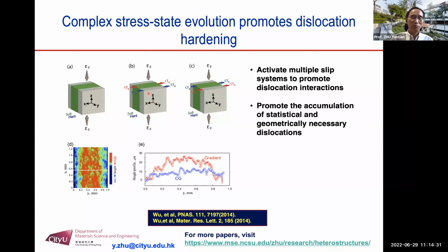And that causes a bigger problem because initially you apply a uniaxial stress. Now you have a two-dimensional stress as a result, because the center cannot shrink freely. It's constrained by the surface layer. On the other hand, if the surface nanostructure layer also starts to deform plastically, we know the surface layer has a low strain hardening rate.